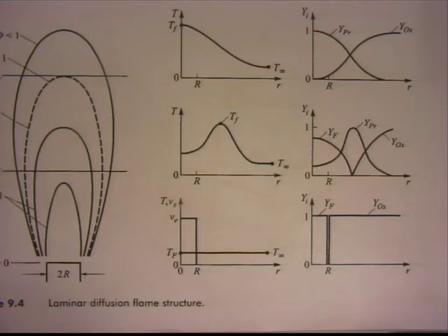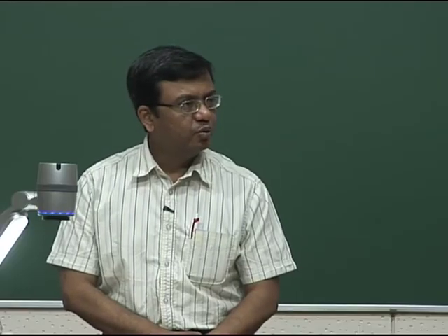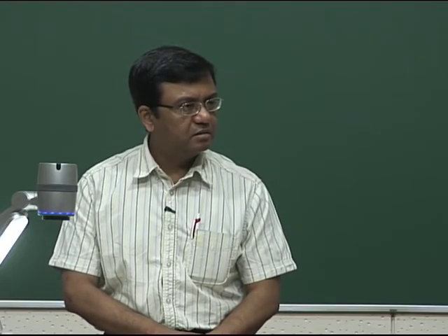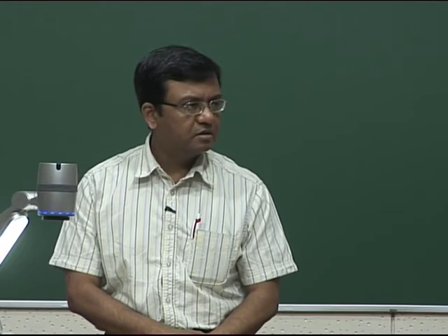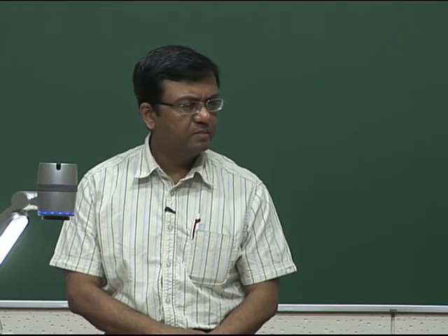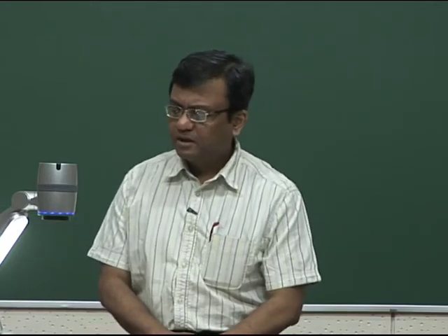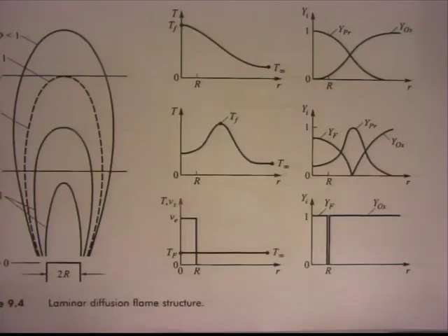Can we relate this with rich and lean mixture? Okay, so the question here is, can we relate this to rich and lean mixture? Okay, so we have to see this question in detail, but what do you think? It should, right? It should matter, because the reaction rate will depend on whether the mixture is rich or lean. Okay, but then there is a problem. This is not a mixture that you are sending, right? Are you sending a mixture? It's not a premixed line. You are sending only the fuel.